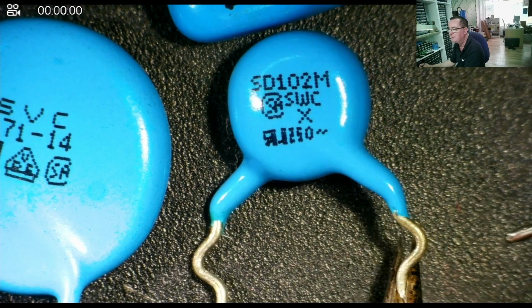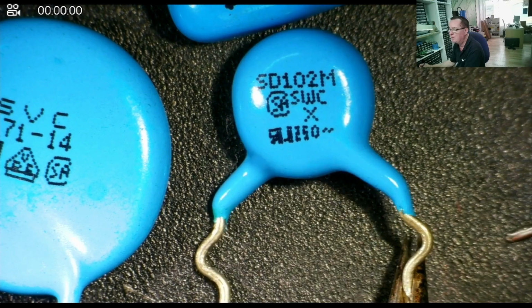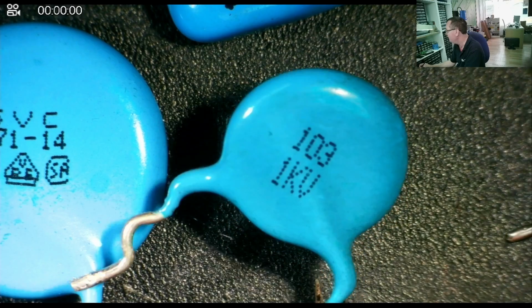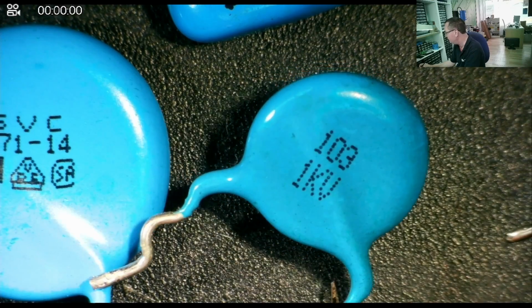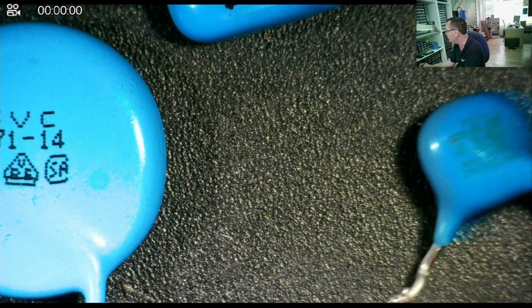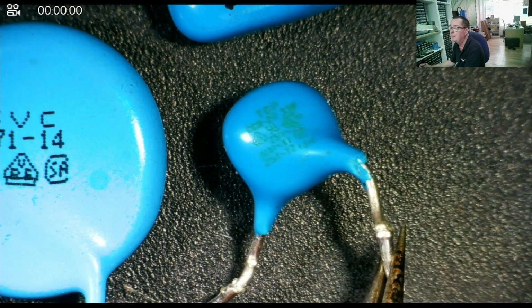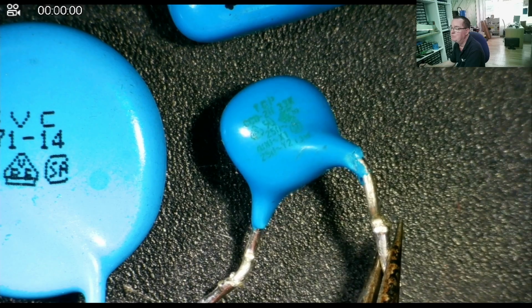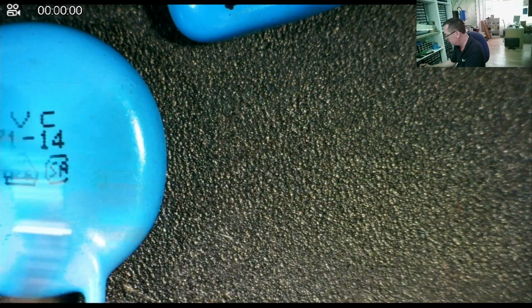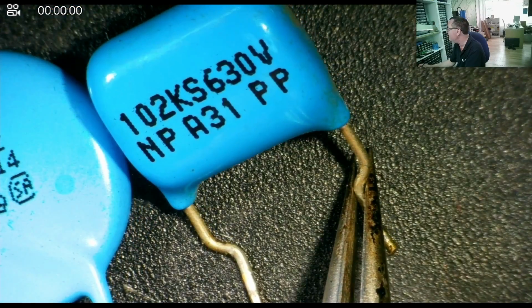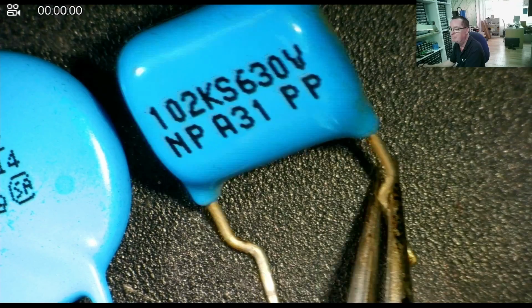This is SWCX. This X capacitor is another filter capacitor, whereas that is a high voltage capacitor, high voltage DC. These are not the same things, and they have some rather unusual markings on them. I would suggest, again, this is, you see, X1Y2 filter capacitor, 250 volts. You need to be sure when you're replacing these types of capacitors if they're faulty.